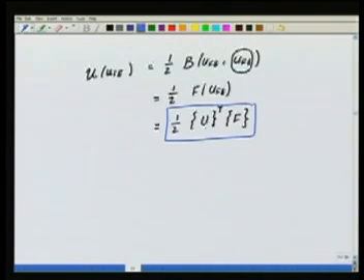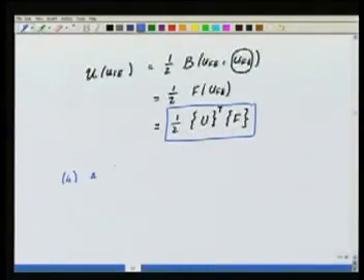So I solved for the u transpose, somehow I store the load vector, then this is load vector after applying all the boundary conditions, then u transpose f should give me what is the strain energy. Okay. So this is very easy to compute, and for the sequence of meshes I should be able to check. Another thing that we should be able to check for problems 4 and 5,